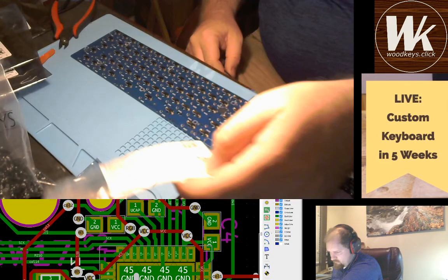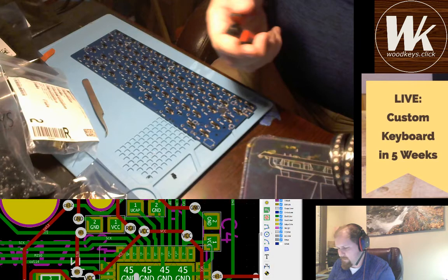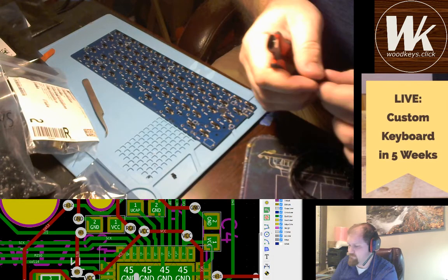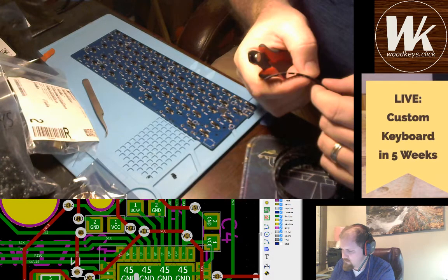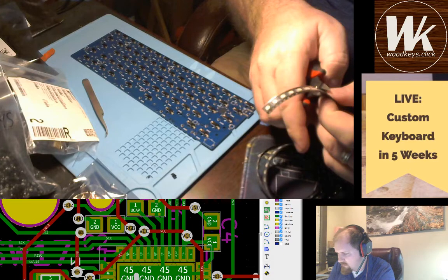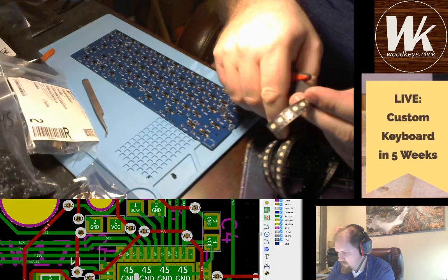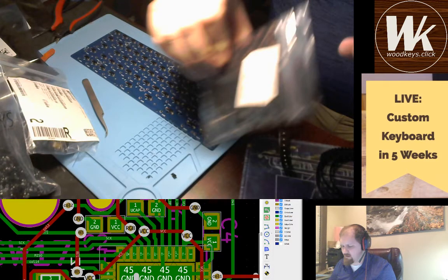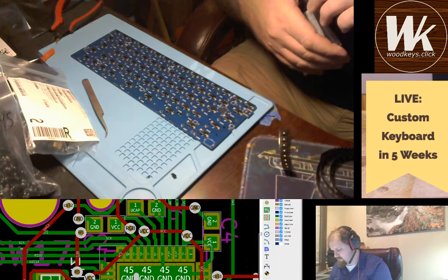Alright, I promised LEDs. Okay, so I found that flush cutters are about the best thing for separating these, for cutting these reels. 8 of these, because you can get them right in there and they just make one nice clean cut. As opposed to scissors, if you get them slightly off, then you might accidentally cut through and dump the next part out.